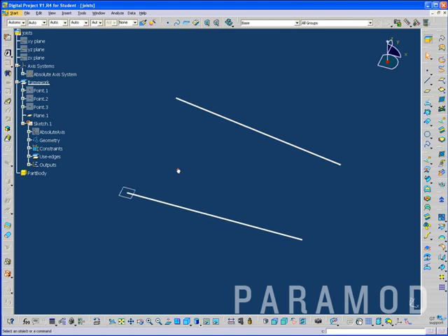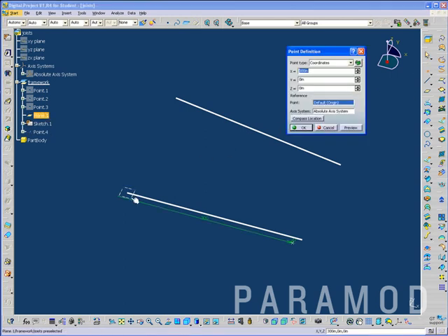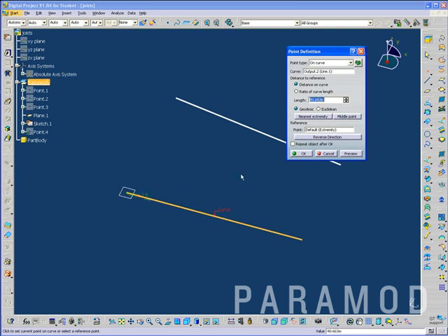If we want to, let's create, well, now we'll just create a couple of points along this line. And so we'll do points on curve, select this, and we'll do distance on curve as 16 inches.